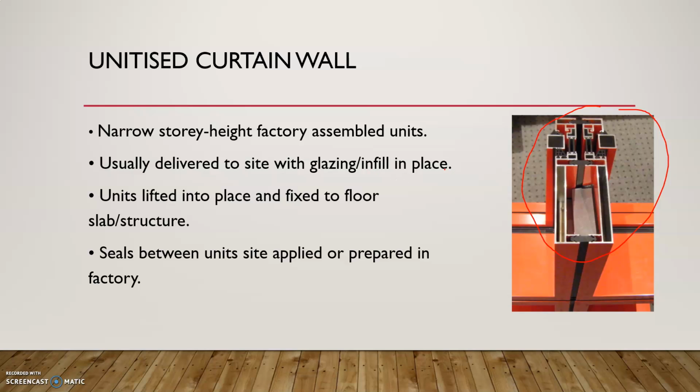So with the unitized facade, they are built-in units and everything, the glass and frame, is built in the factory. Units are lifted into place and fixed to the floor slab or structure. Seals between units are site applied or prepared in the factory.